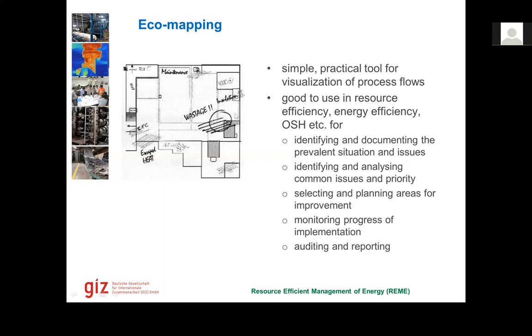So for example, I say this location is A1. And in the A1 location, I have two symbols. One is a hatch line and one is a circle. So in this additional sheet, I would also write in detail, what does this circle mean in A1 location? And what does this hatch line mean in A1 location? So this is an advanced or detailed way we could also use this.